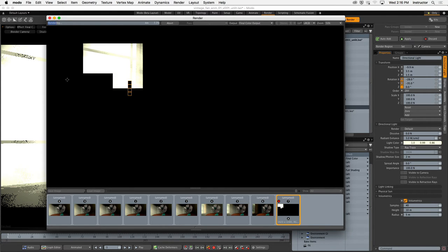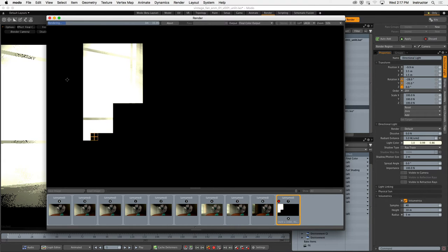Now, one of the things that is kind of a barrier for us right now is understanding the impact of all of these new items and maybe the changes to our shader tree on the render itself. And I hate having to sit and wait for a render to cook just to see what a change looks like, right? Have you guys run into that problem yourselves? You make a change and you're like, I don't want to wait 20 minutes just to see what this one little section looks like. Well, here's today's pro tip of the day: render regions.